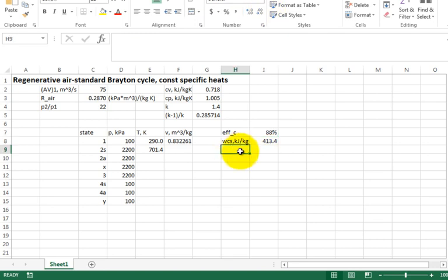Okay. But now because I know it's 88%, isn't the work the compressor needs to actually intake going to be greater, in kilojoules per kilogram? So it's going to be the isentropic work divided by the 88%. So I do it like this in my mind when I solve problems.